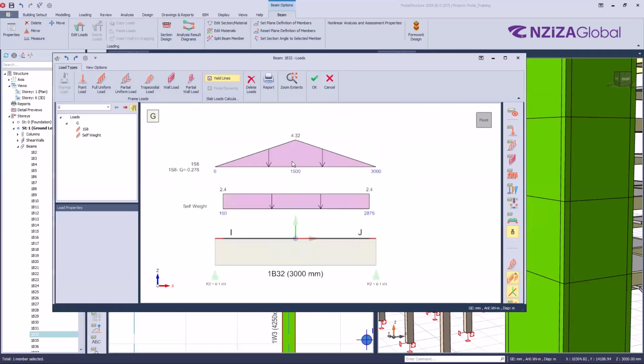Then here at the top you will be able to see the loads which are reaching the beam. Good. So in my case, I have this rectangular beam. I made this rectangular load, which is the self-weight. I have these triangular loads, which are coming from slab 8.